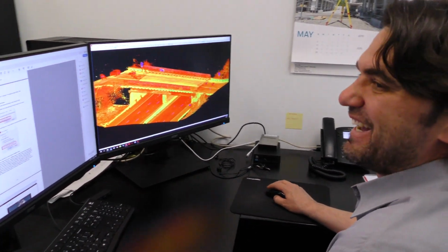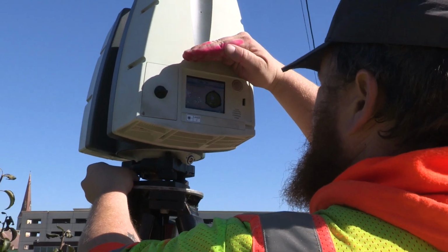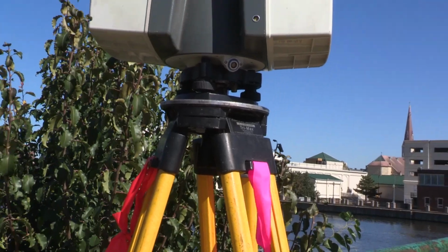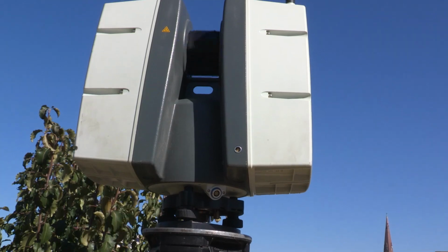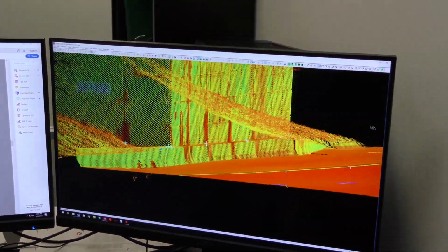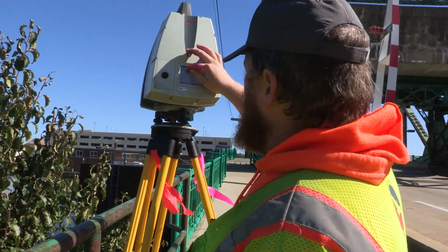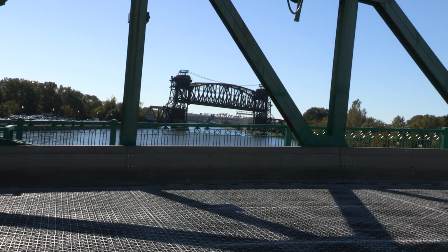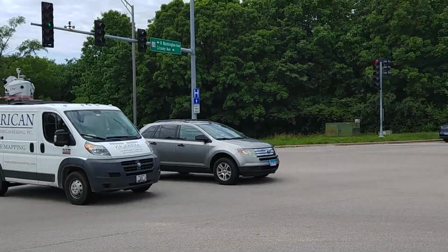Typically in subsurface utility engineering, all of the latest surveying techniques are used by our organization. So we use kind of a combination. Primarily we use GPS, secondarily we'll use a total station, but then we can also use LiDAR in some situations. LiDAR is real helpful for us when we're in a situation where we need to capture the topography information, but it's difficult for us to go out and capture that information.